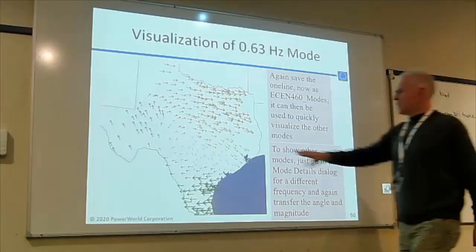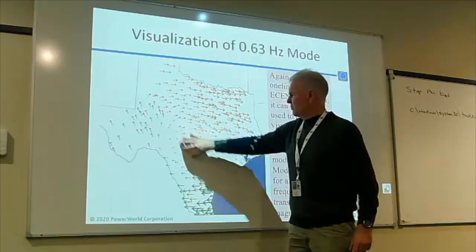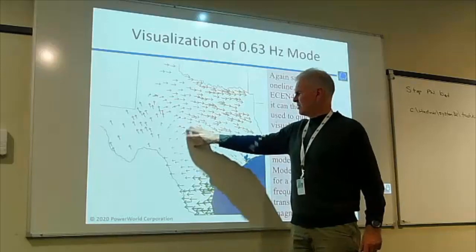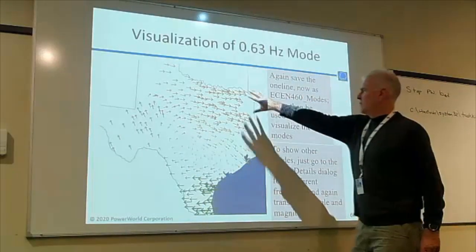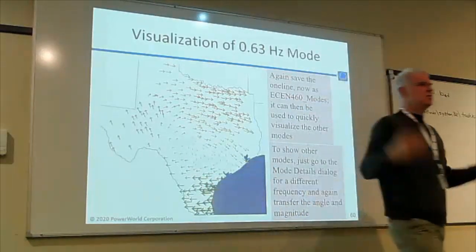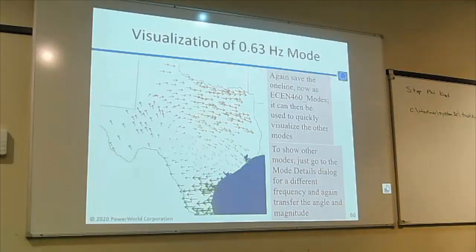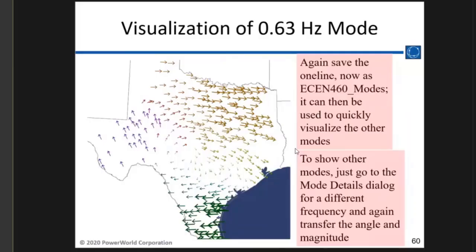You're not going to do much in this part of the system with damping that because it's sort of oscillating around there. But if you're up here or down there, you might be able to do something with it. So it's giving you insight into the problem. And of course, in WECC, you guys know the different modes you have. But if you have a severe contingency, those modes could switch around. This is something that could tell you how those modes are switching around based on actual data, like PMU data, and you can visualize it as well.